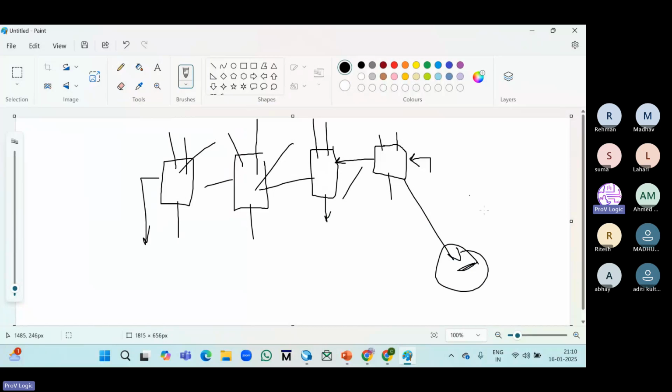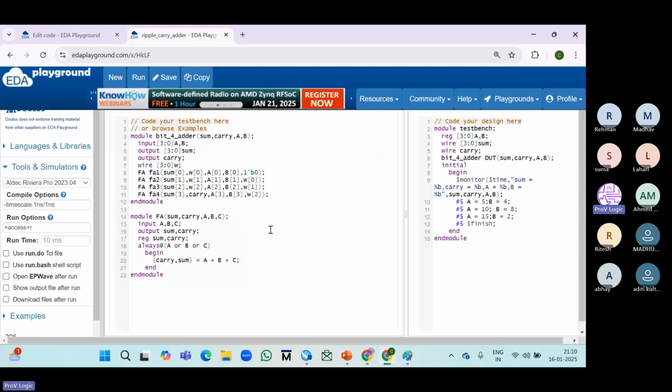Now if you write the program for the full adder, that means a test bench, it will generate for the full adder test bench. If you write for the ripple carry adder, it will generate for the ripple carry adder. That also you need to write separately, not in the same block. If you write in the same block, it will provide parallel output because the flow is parallel execution. So how is the programming style? See here, on the left side, the 14th line. If you observe the 14th line, module, name of the module, full adder, FA.